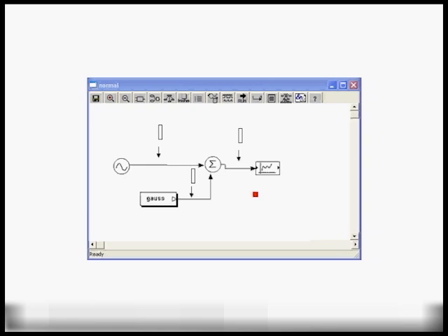This is especially important in doing bit error rate simulations, where you might generate, for example, 1 billion bits in order to determine the bit error rate in a fiber optic communication link, for example. So this is a case where we don't have much issue. The footprint is bounded, and we don't have multi-rate signal processing or feedback, and those are the topics we'll get into in the next section.